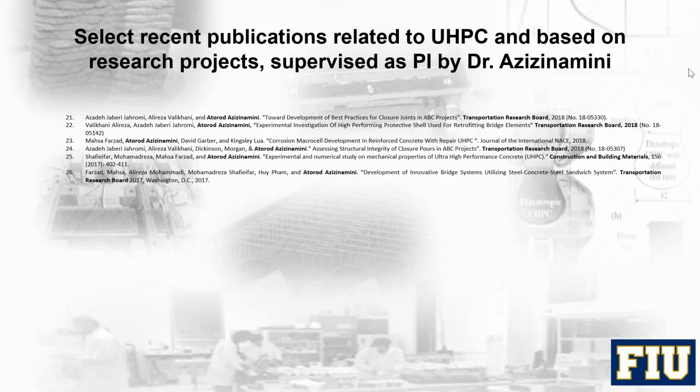So nothing really penetrates. That's why I think for bridge deck overlays, for example, the UHPC is a fantastic solution because you're going to seal it up. You're going to add to the strength as well. So it's durability and strength. So it's a good solution for the areas where you expect very harsh conditions.